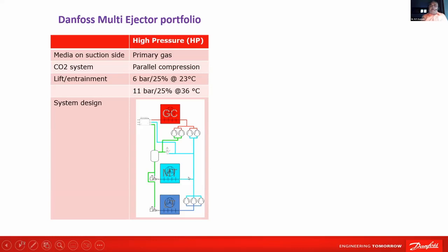Medium temperature compressor suction to the compressor, discharge through the gas cooler, ejector. Medium suction vapor is also sucked through the ejector, and raised in pressure, it goes into the intermediate pressure. Now from intermediate pressure, we suck into another compressor. This is called a parallel compressor.